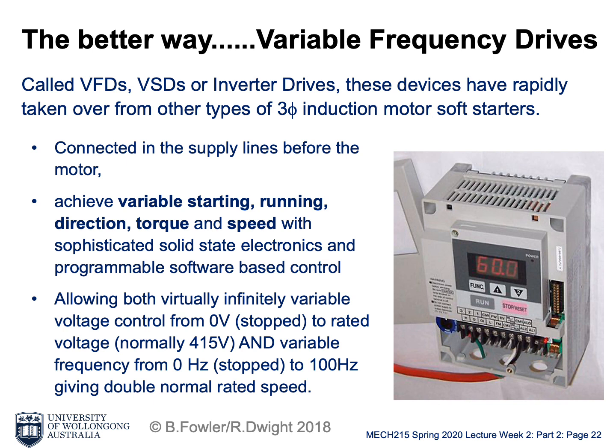So this virtually provides unlimited possibilities for the motor to run. During startup, you can program different frequencies and different power supply to change the features of the motor supply. But obviously, this is a much more complicated device compared to the starter. It will be more expensive, but it's still being used more and more to replace the soft starter or just connecting the motor directly on the line.